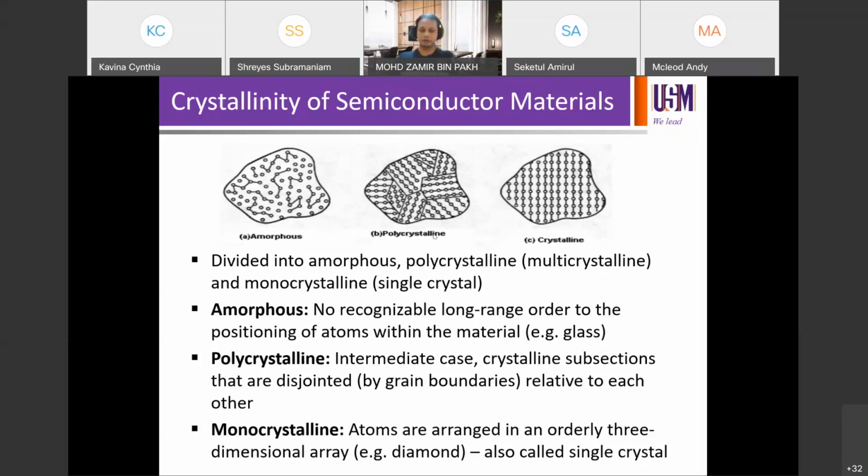So in polycrystalline material, in every single grain, you have a single crystal inside. You have grain boundaries wrapping the grain. Inside, all single crystal, and the neighboring grains, all single crystal. But since you have multiple grains within the wafer, for example, then we call it polycrystalline or multicrystalline. Multicrystalline normally is the reference we use in the solar industry if you talk about visible grains.